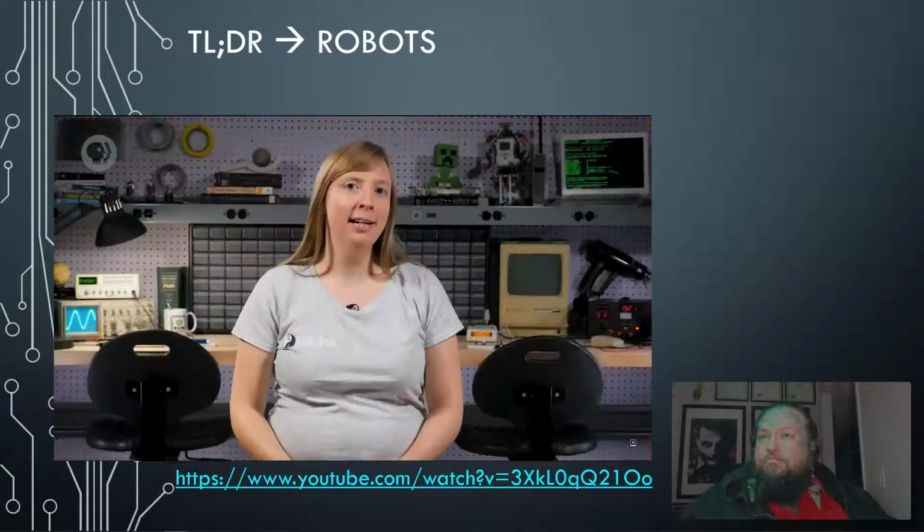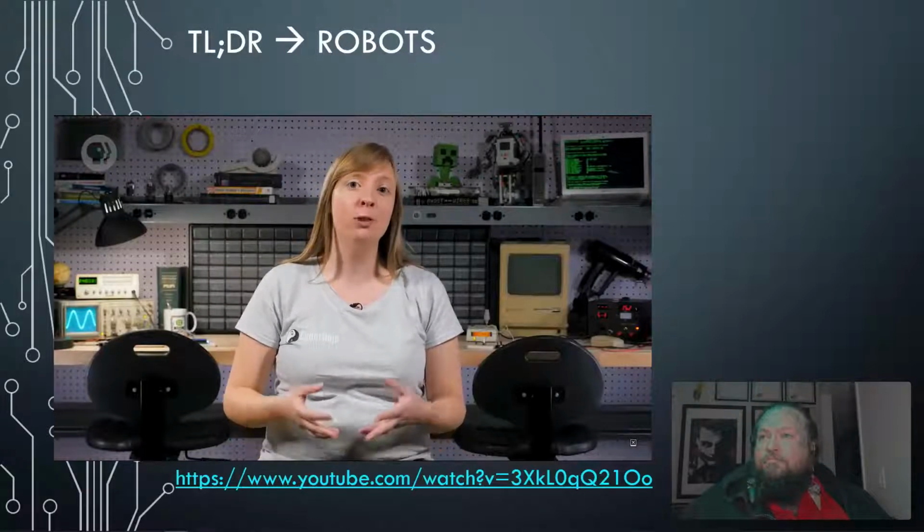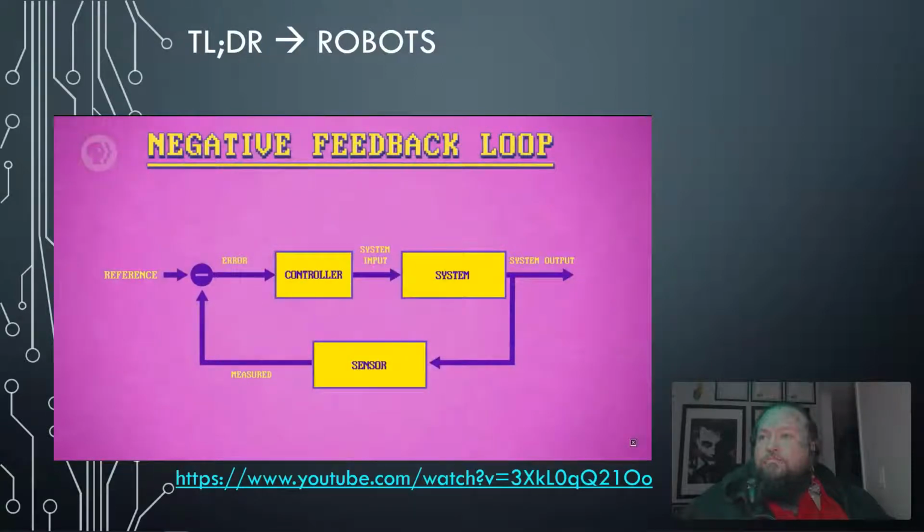Because we're trying to minimise the distance between the sense position and the desired position, this control loop is more specifically a negative feedback loop. A negative feedback control loop has three key pieces. There's a sensor that measures things in the real world like water pressure, motor position, air temperature, or whatever you're trying to control. From this measurement, we calculate how far we are from where we want to be, the error. The error is then interpreted by a controller, which decides how to instruct the system to minimise that error. Then, the system acts on the world through pumps, motors, heating elements, and other physical actuators.